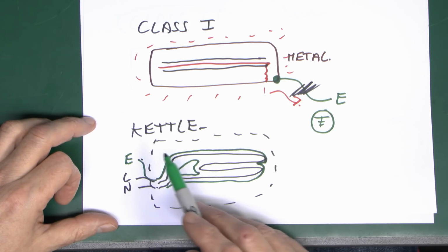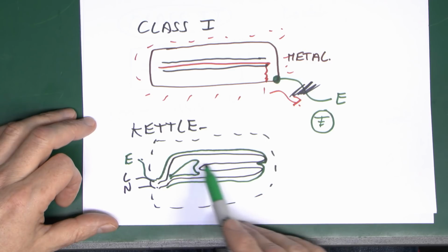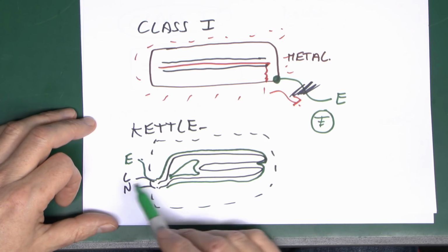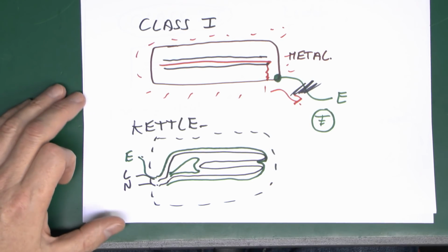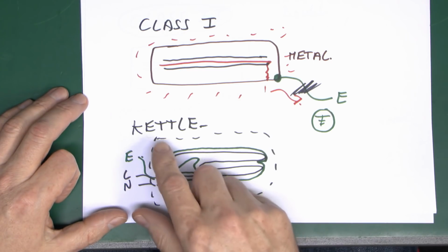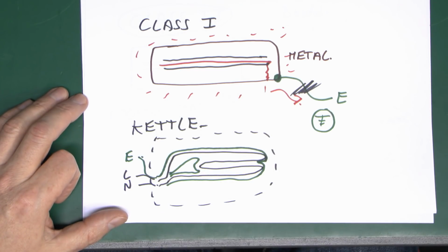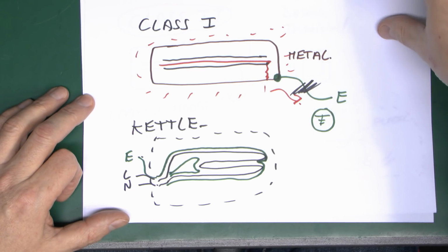And the same applies to most plastic kettles. Although the whole kettle is actually plastic, inside it's going to have that steel cased element. So again, if a problem occurs with that, it causes the same effect, so it disconnects the supply from doing that. So if you're going to test a kettle, just beware that you're not testing to the outer covering. In most cases, actually the outer casing of the element. And in a lot of kettles, you can't actually get to that anymore because they have these sort of flush bases inside to make it easier to clean.